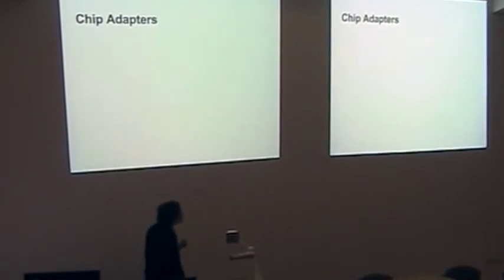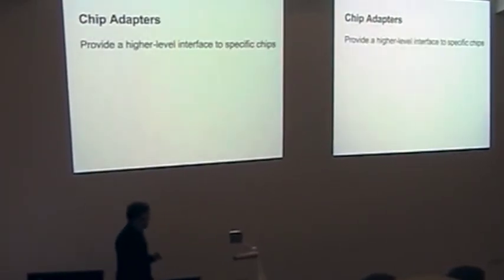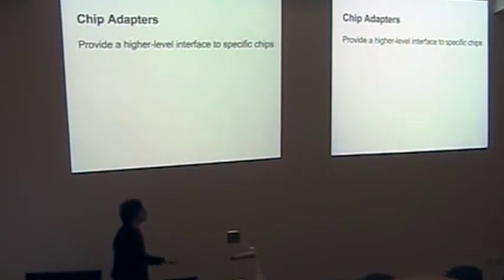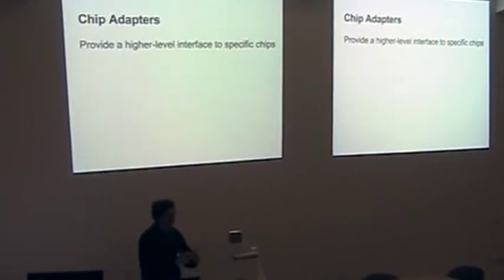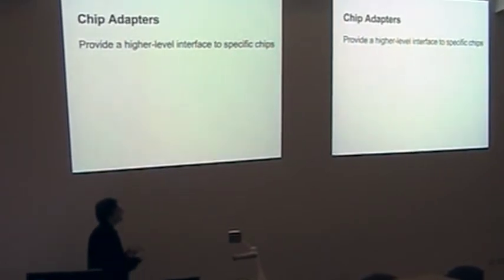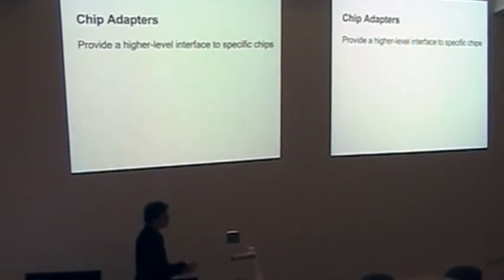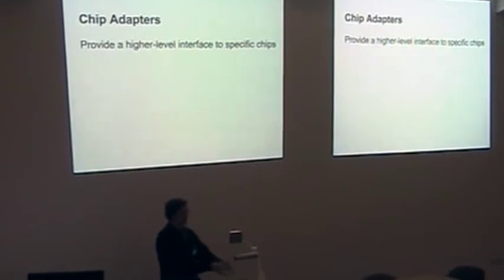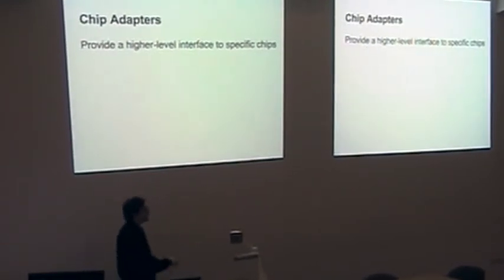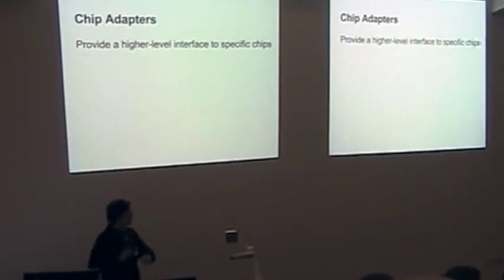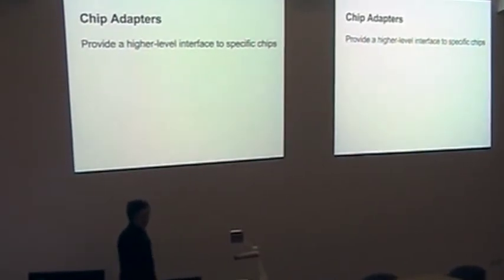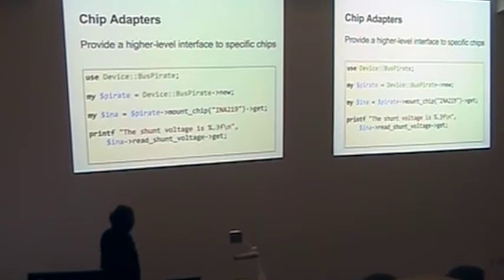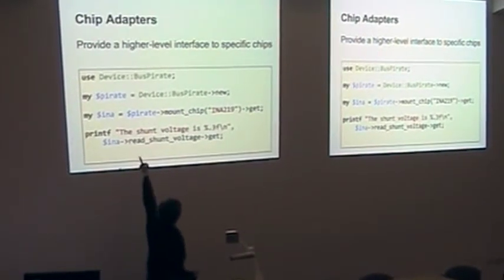But still kind of low level, because most devices you're going to want to talk to, you're not innately going to decide, oh, I need to write a command with these bytes down in. You want to do something even higher level. If you've got an LCD display attached, you just say, I want to write the string here on the screen, or if you've got a temperature sensor, you just say, I want to read the temperature, please. So I wrote a whole new layer on top of the bus pirate device, chip. So this one is even nicer.